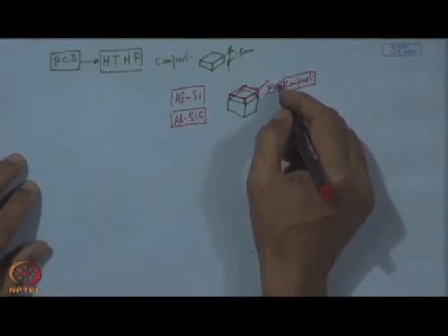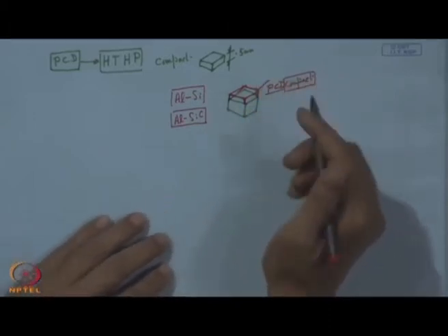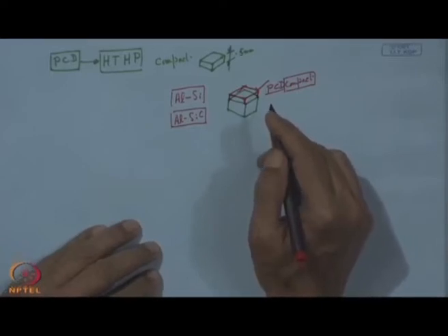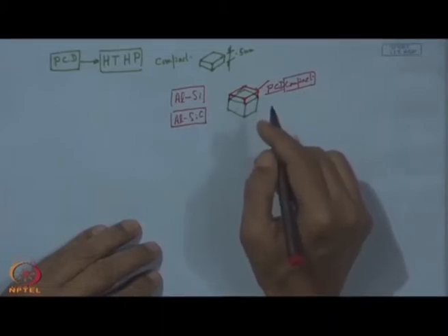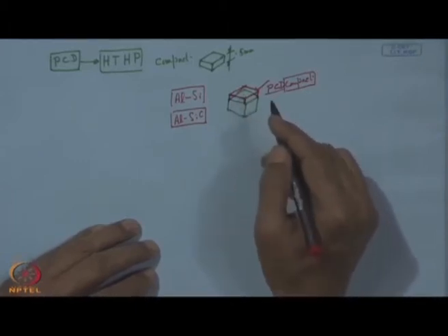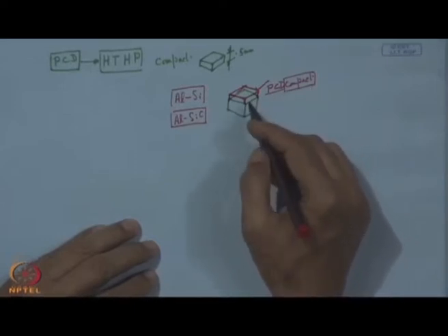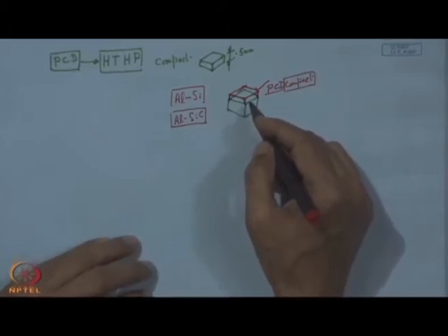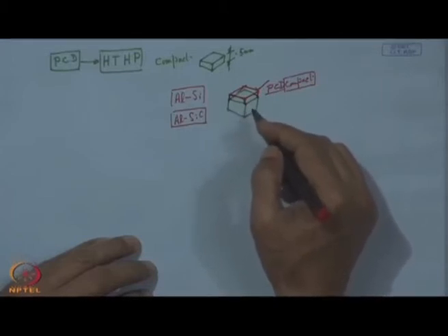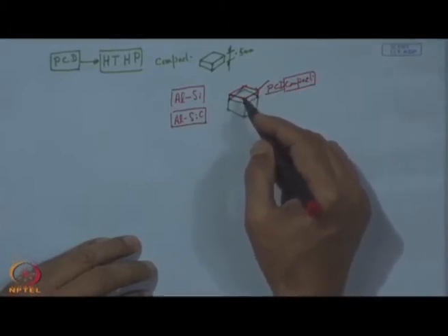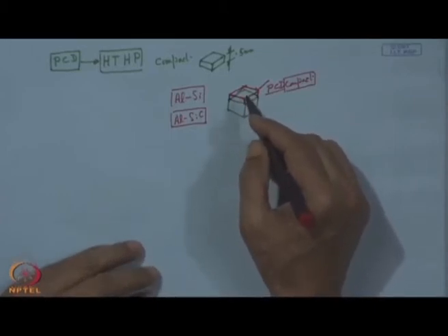That means high temperature stability has certain limitation, and another disadvantage of this tool, one can immediately find out, is its limitation in terms of tool geometry. Now, this tool of this given shape can be well used in turning, facing, or in some general purpose milling cutters, but when it comes to drills of different or very small size, or end mill cutters used for pocket milling having some complex geometry, then this particular compact cannot be easily given the shape to suit the geometry of that small rotary tool.